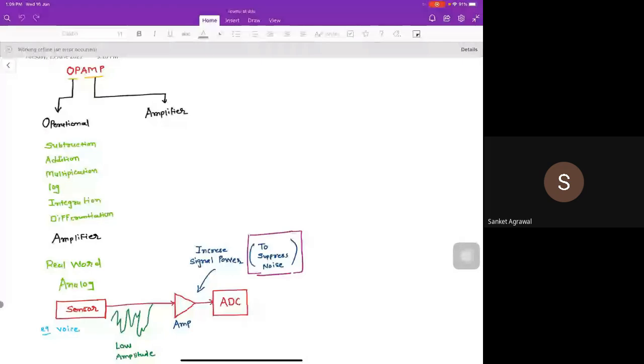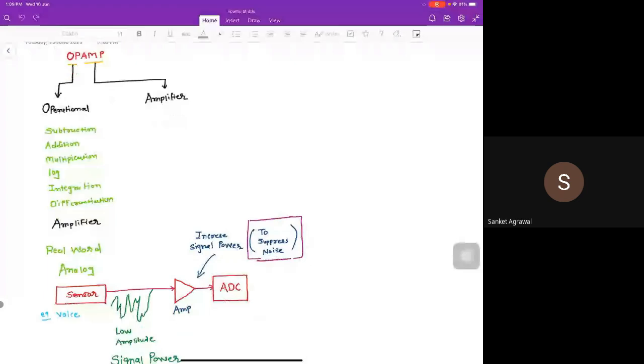So, operational amplifier. One more thing that I want to tell you is why the op-amp. You have heard that the op-amp requires high gain in a negative feedback system. We require a high gain feed-forward path because finally, in the negative feedback system, we want the whole system to depend only on the feedback path, and the feedback path is only passive elements. We don't want the feedback transfer function to depend on the feed-forward transfer function. That we will see step by step.